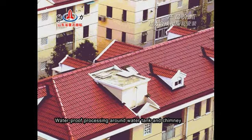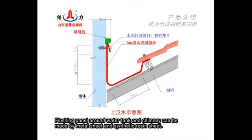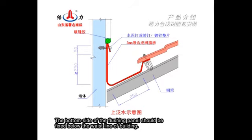Waterproof processing around water tank and chimney. Flushing panel around water tank and chimney can be made by metal sheet and synthetic resin sheet. The bottom side of the flushing panel should be fixed below the waistline of the building. The upside should be fixed on the top of the purlin and below main tile.